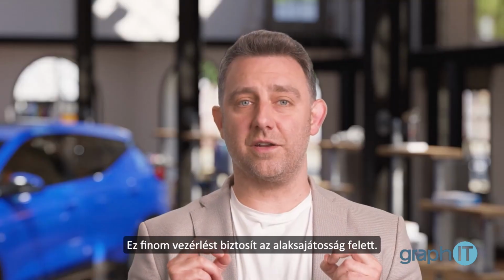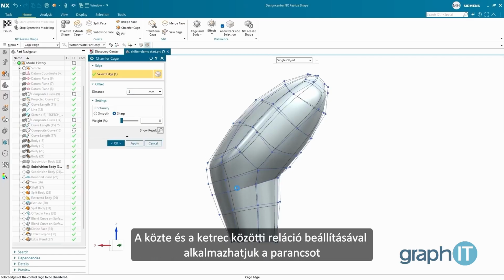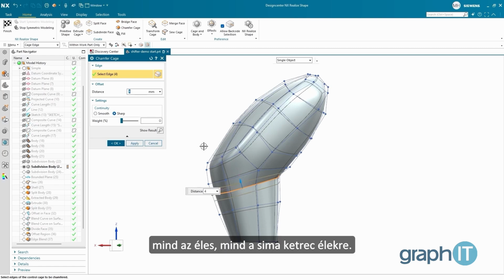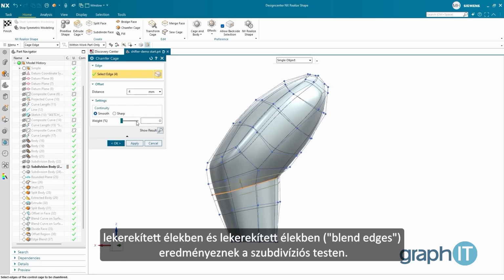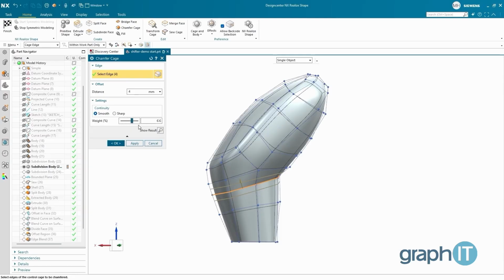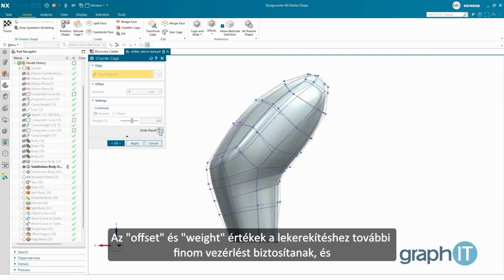This gives you fine control of the feature by adjusting the relation between it and the cage. You can apply the command to both sharp and smooth cage edges. The continuity setting has sharp and smooth settings as well, which result in chamfer edges and blend edges respectively on the subdivision body. Offset and weight values for the chamfer provide additional fine control, and you can preview the changes in the graphics window before you commit.